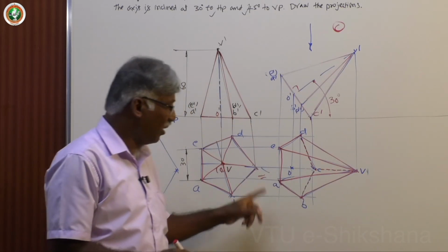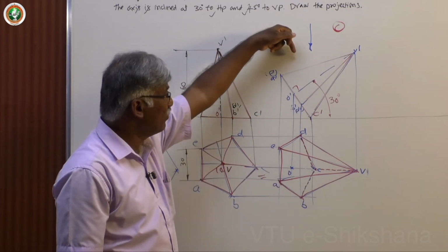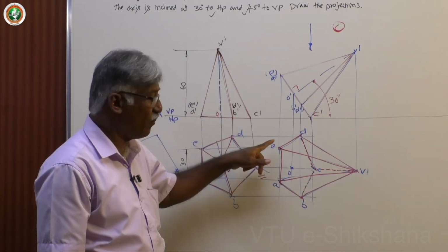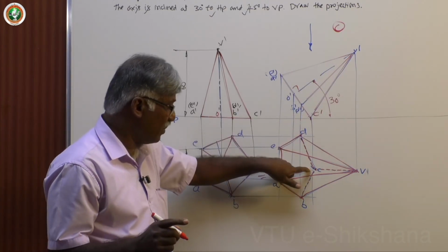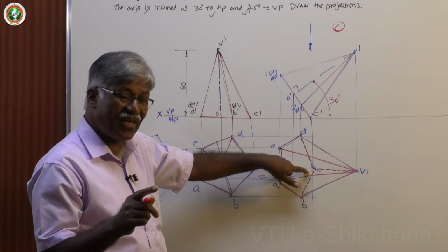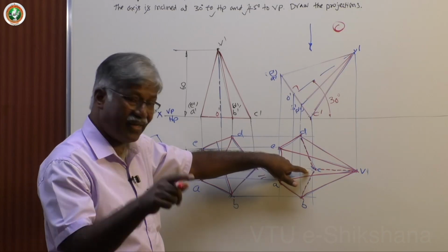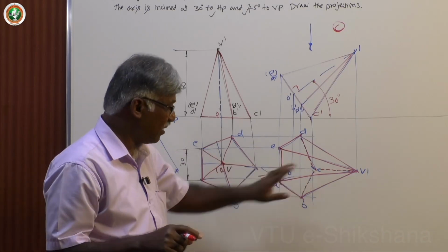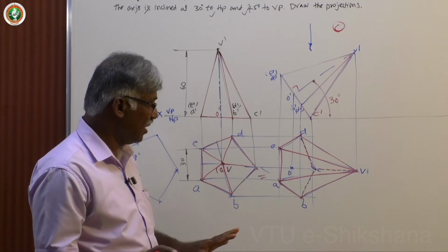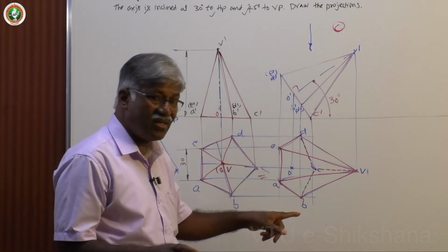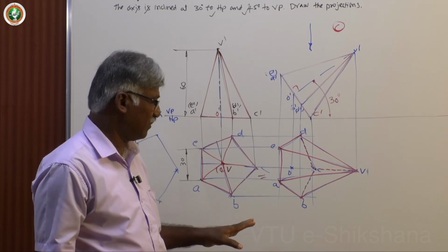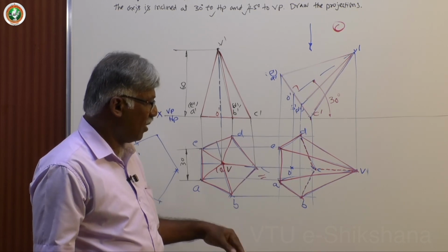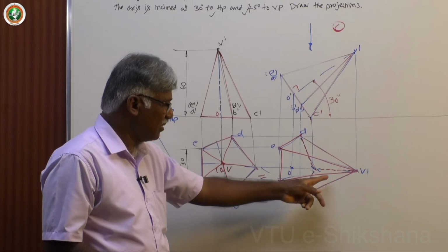Okay. Now, I will repeat, if you look from this direction to complete the second figure, top view, C is the farthest item from you, that is not visible, and any number of edges, either slant edge or base edge, connecting to that are not visible. So, hidden lines. Rest of the lines all are dark, and see that all boundary lines are dark, that is always there. Okay. Next, we have completed all edges, visible, invisible.